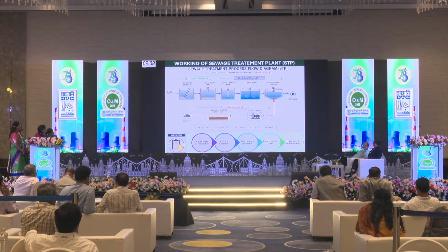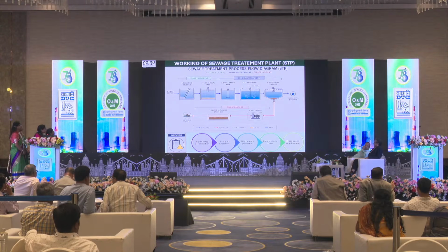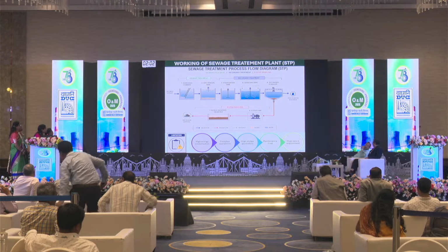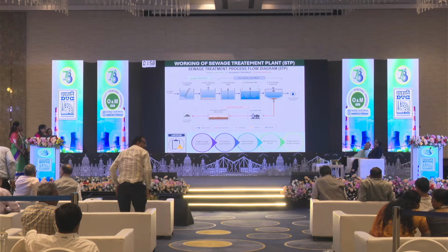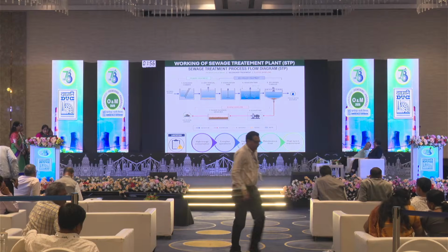And then it is collected in the secondary clarifier, where the sludge deposits in the bottom, and it is disposed of after the sludge handling process. And the treated water is disposed of after treating through chemicals for maintaining pH.